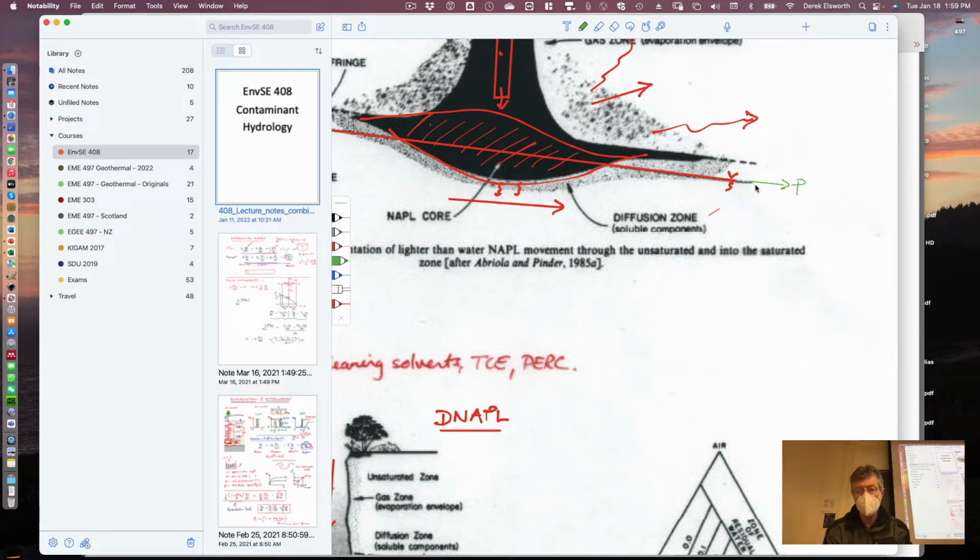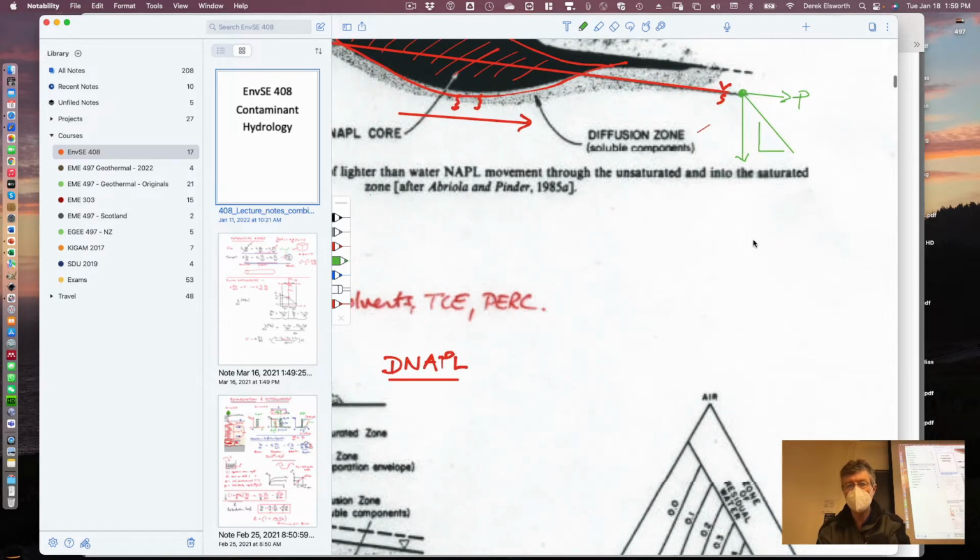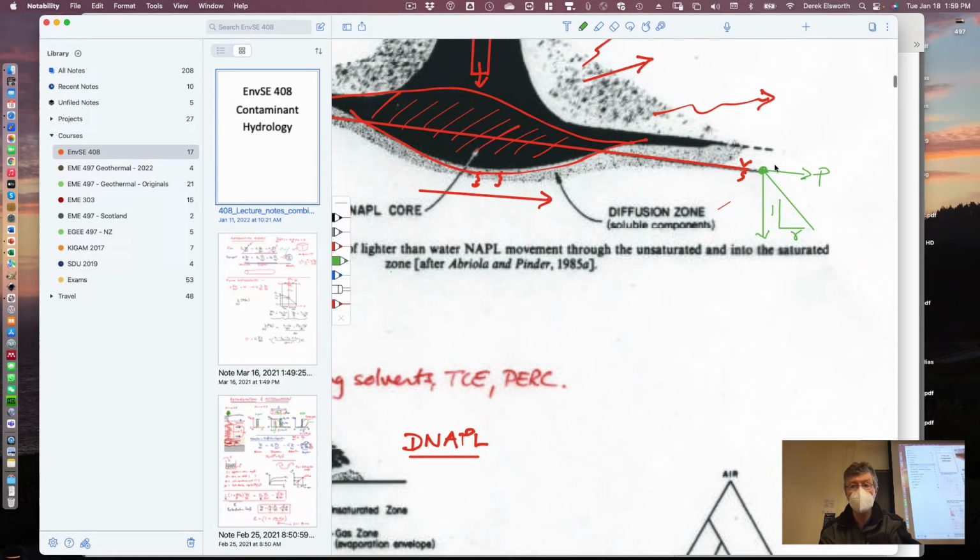If you measure pressure with depth, that we just did, then by definition the pressure at this point has to be 0. It has to change according to what we said before. I see people's eyes straining. Is my writing bad and poor? So this would be unit weight. This would be 1. This is the gradient of groundwater pressure, just like going down in a swimming pool.